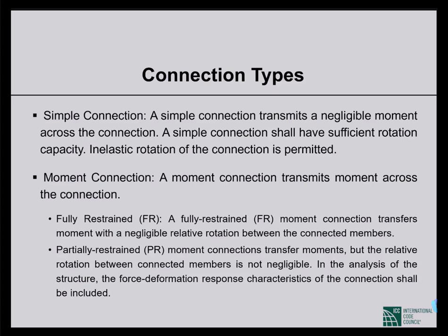However, since it doesn't transfer the moment, the connection itself goes under rotation, and we have to be sure that the simple connections have sufficient rotation capacity. And inelastic rotation is also permitted in case of simple connection.